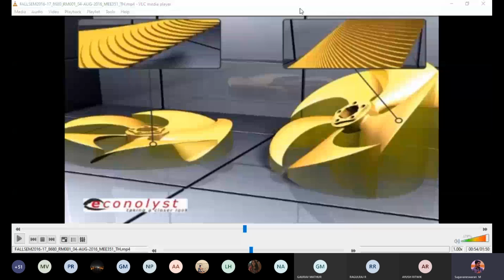Sir, will the first one have better dimensional accuracy? Why? What is the reason? Sir, because the structure is horizontal and this is slanting, so while depositing, there might be material flowing or something. Is that possible, sir? Correct. Anything else other than this? Sir, I guess the second one is better because the support material and actual product demarcation lines are very specific and clear. Okay, correct. Thank you.